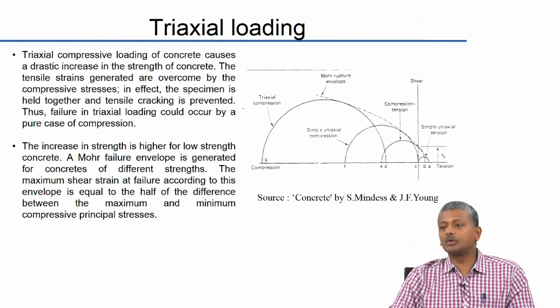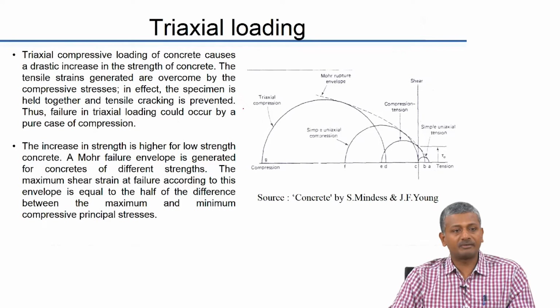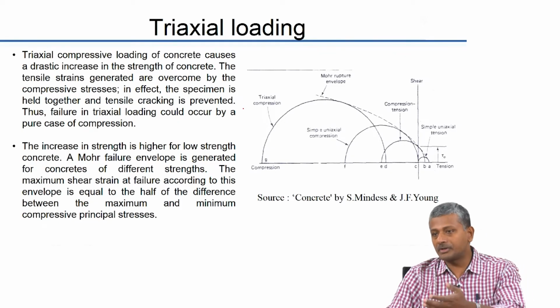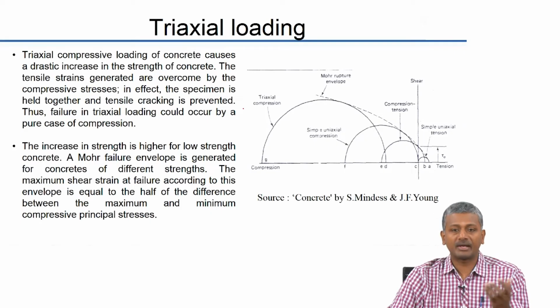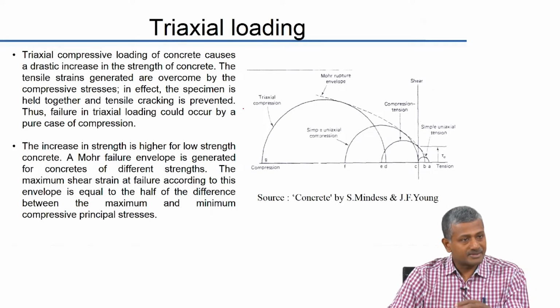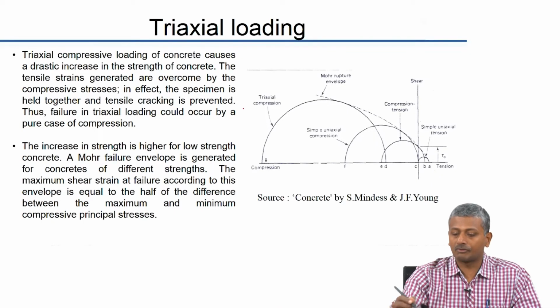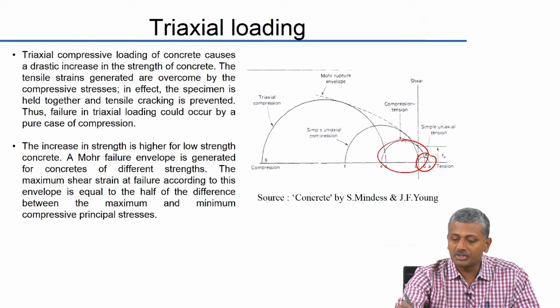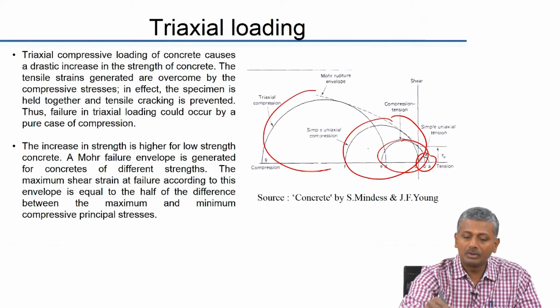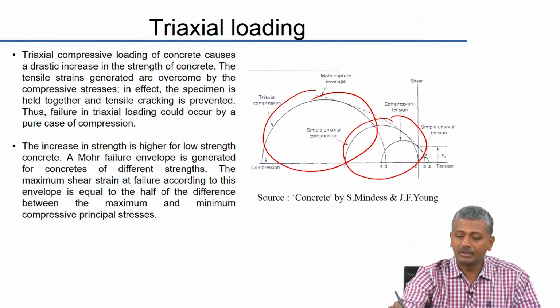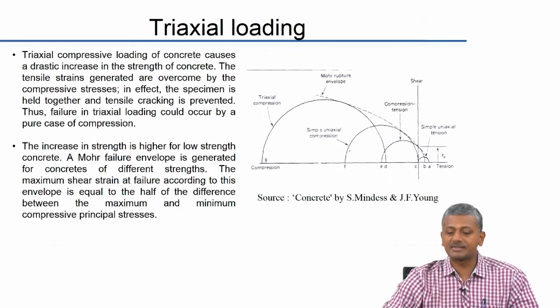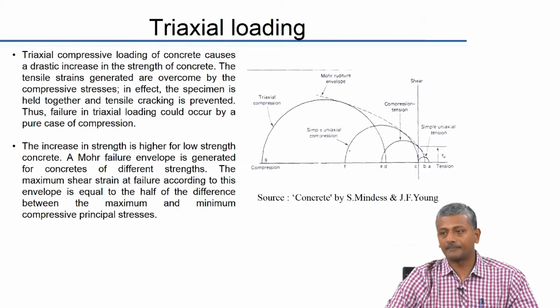Now, in the triaxial loading, of course, you have learnt this before. You have changes in the states of stress from pure compression to compression tension to triaxial compression or triaxial tension. In this case, you are changing from a tension to a compression tension to pure compression to triaxial compression. What happens is that you see a gradual increase in the extent of stress that will cause failure.